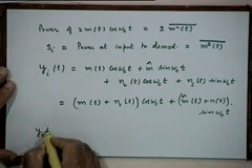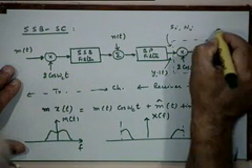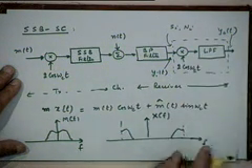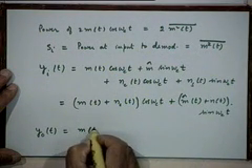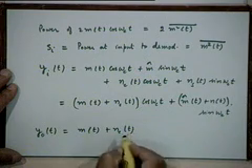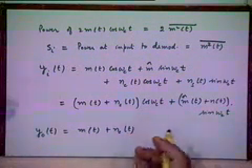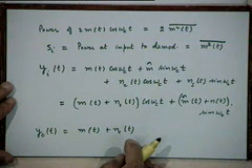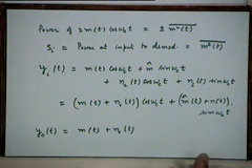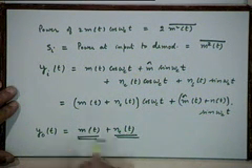So, output of the demodulator, if I call it Y sub OT, then Y sub OT essentially will be mt plus n sub ct, because when you multiply with 2 cosine omega ct, you will get 2 cosine square omega ct, which is equal to 1 plus cos 2 omega ct, and the only part that will be left after low pass filtering will be mt plus n sub ct, right. This is the signal part of the output, this is the noise part of the output.